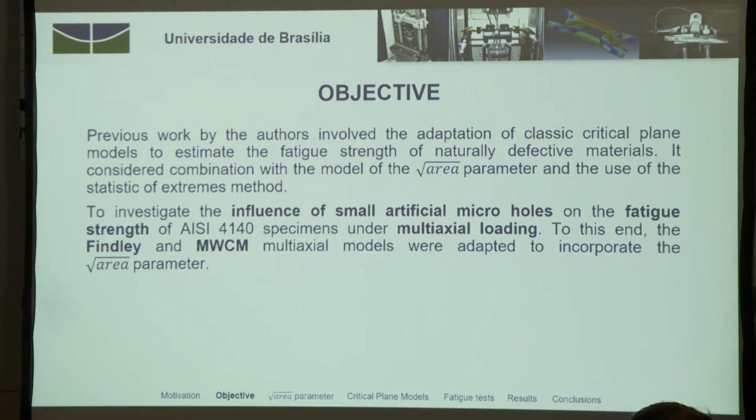In this work, we are introducing artificially manufactured small defects in samples of the 4140 steel taken from the crankshaft that failed, and also coupling with the Findley and the MWCM multiaxial models in order to estimate the multiaxial fatigue limit of this material.